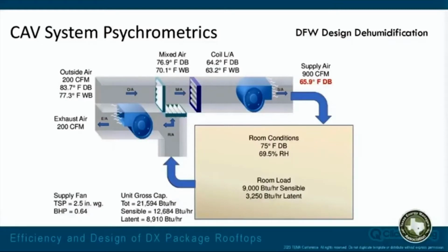By dropping the airflow at full load on our constant volume system, now we have that same lower airflow, and we gained on it compared to what we had before, but we're still well outside what is recommended by ASHRAE and what's needed for occupant comfort and for protection of the building. As things get too humid, it can cause problems within the building as well.